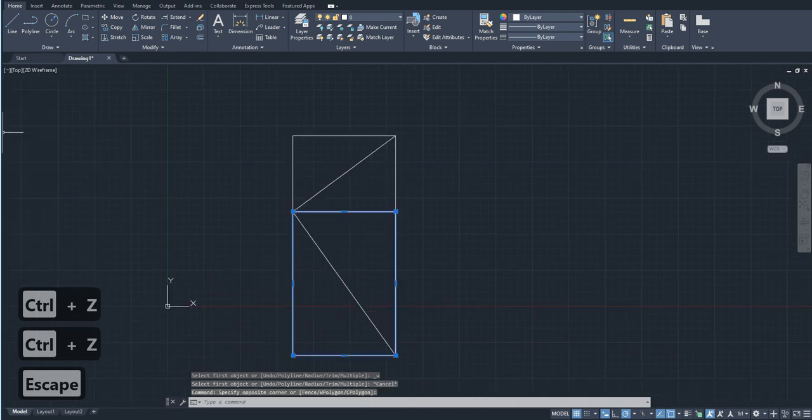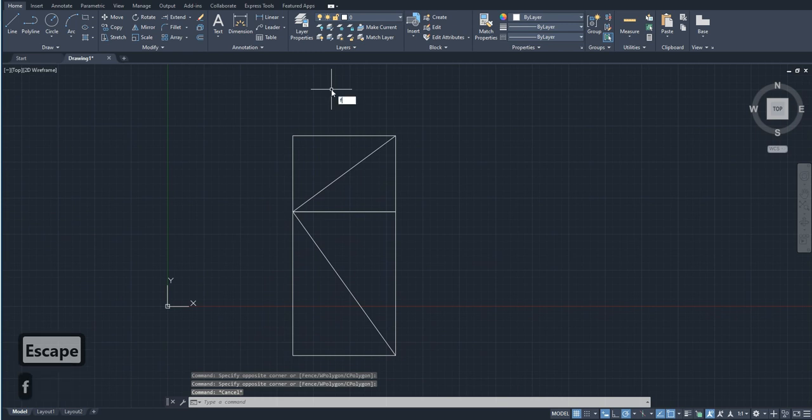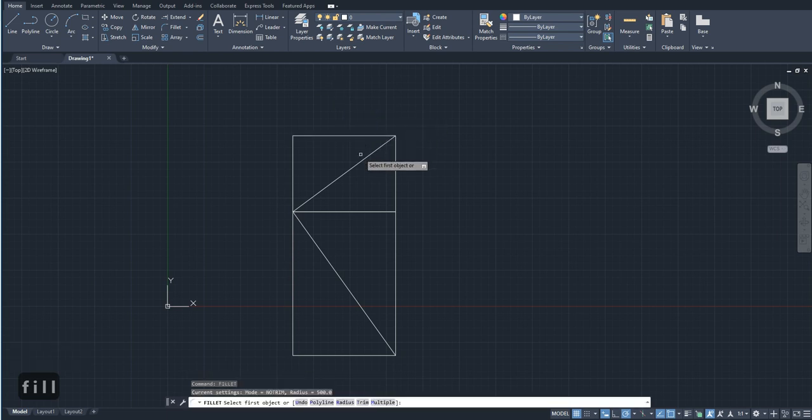But to do this very quickly, I had this as a polyline. This particular thing is a polyline, and so is this particular object. So to do this a bit quickly, I'm just going to enter fillet, and this time I'm going to use polyline. So if I just select the polyline, that's what it's going to do. It just created corners over this polyline.